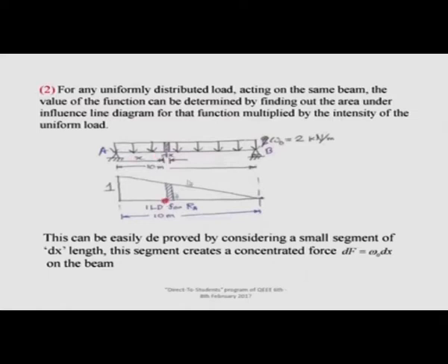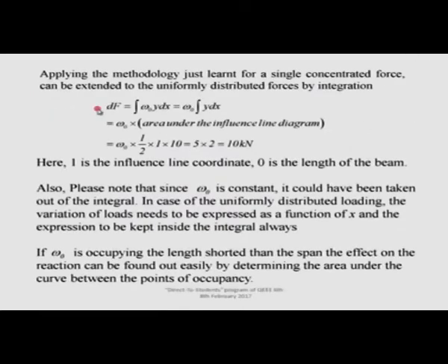Yes, I can, and for the infinitesimal length, suppose the length dx, it will lead through integration to the sum total effect of the uniformly distributed load or any varying load. Basically, it is the integration. So I am not really restricted to uniformly varying load. I can find it from other loadings as well, since it is a differential element. And you can find by integration the effect: dF is equal to omega 0 into dx for this elemental loading, and for the total loading it is F equal to the integral of omega 0 y dx.